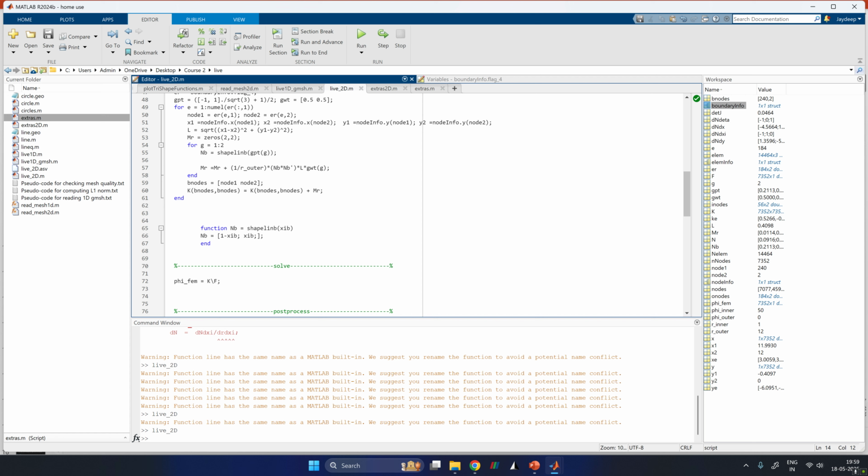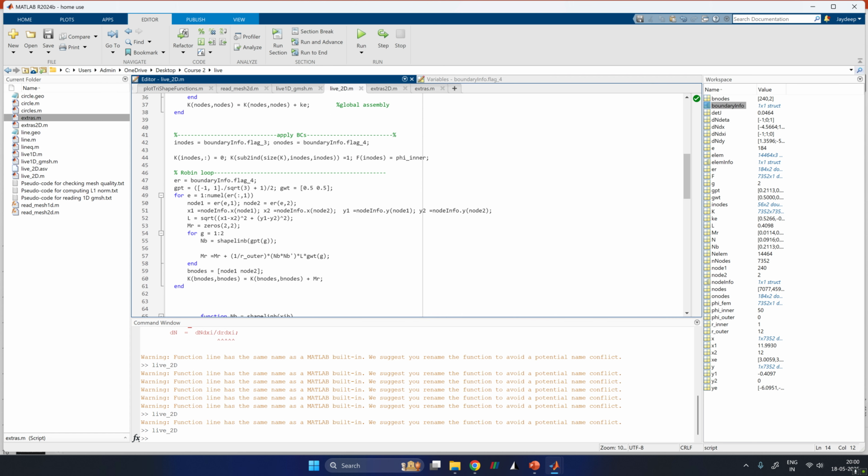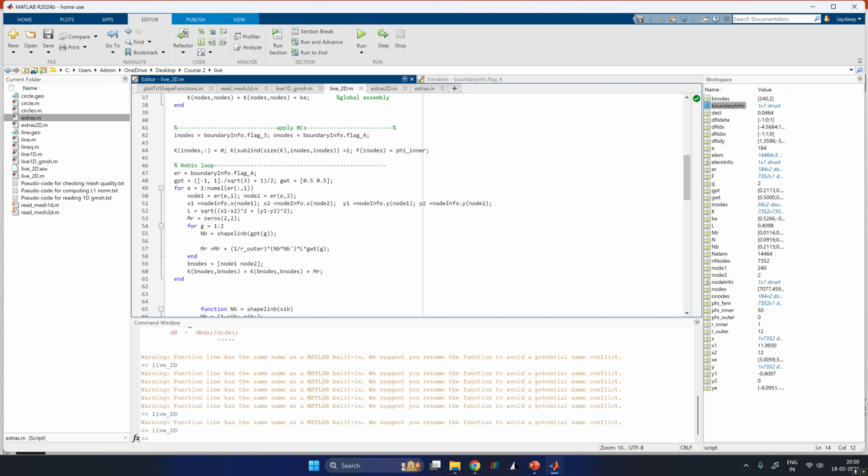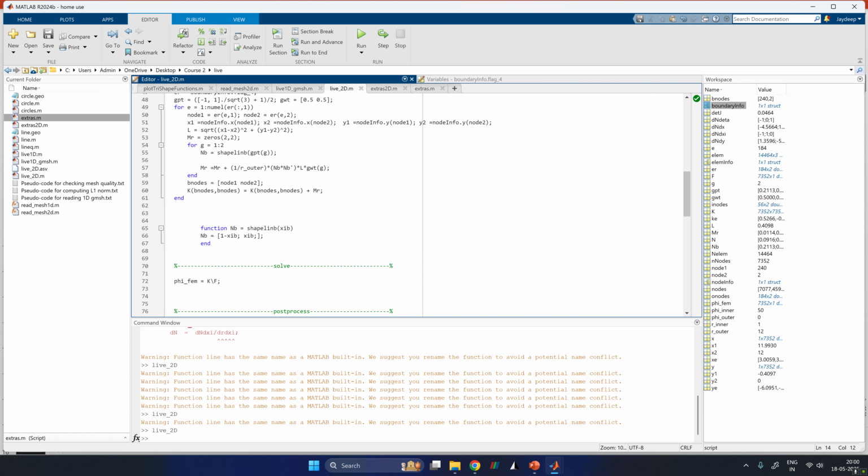In finite elements you will have to do the integration everywhere, so you will have to have the Gauss points, and you will have to ensure that the integration is with the correct number of Gauss points. You can't even add very high number of Gauss points, or else your solver will just stall. Your Gauss points are the innermost loop, and if you blow this up, then you will get very slow performance.